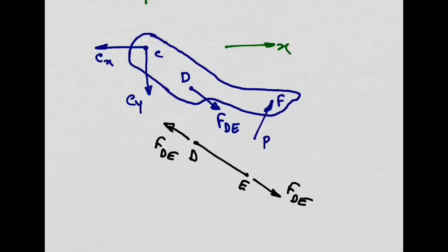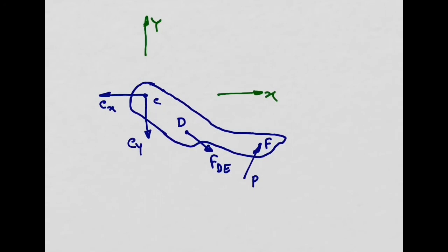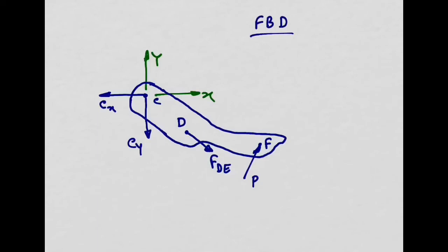All right? So this is all I have in my free body diagram in blue. Coordinate system there, all the reactions and external forces applied in my body. So I can say this is my free body diagram. And now the only thing I need to do is to build the equivalent system, force moment for this one in blue, and say that resultant of the force is equal to 0. Summation of the moments about any point you want equal to 0.